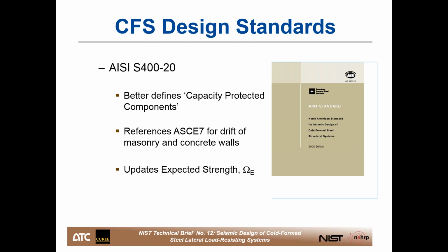And S400 has always used what's called capacity-based design principles, but the specified value of the expected strength factor, omega E, that we use in S400 for shear walls in earlier versions was such that overstrength always controlled. So when you were doing a seismic design, S400 would tell you that you could use the lesser of expected strength or forces from the applicable building code with overstrength, but it turned out that overstrength forces would always control. So S400-20 adopted a more realistic approach that determines expected strength based on the expected strength of the seismic force resisting system itself and additional strength that results from the attachment of finishes such as added layers of gypsum board, plaster, or EIFS. Steel deck diaphragm provisions were also added in Chapter F of S400-20, including methods that could be used where special seismic detailing is required by the applicable building code.